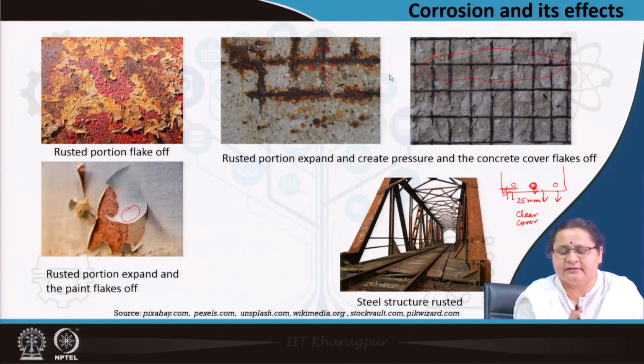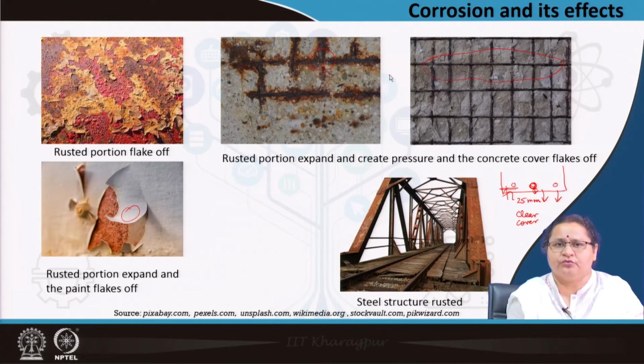So, you can understand this rusting has happened in absence of open atmosphere, but the trapped air, trapped moisture has led to such corrosion. There may be fine cracks which were not visible, through which air has passed through, and this has taken a long time, a gradual process, but it has ruined the concrete. So, corrosion has a far reaching effect onto building, even if the steel or iron is embedded. So, we have to be very careful on that.